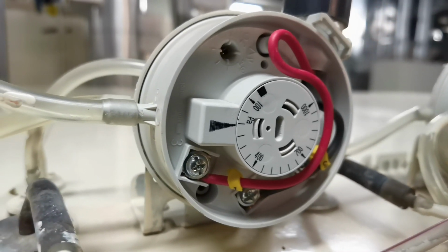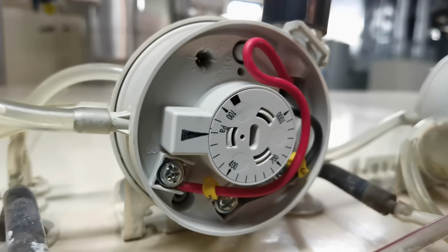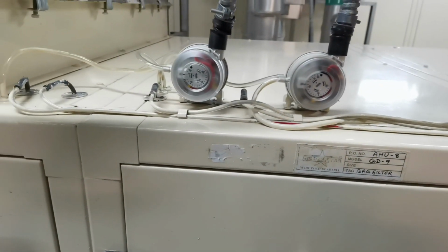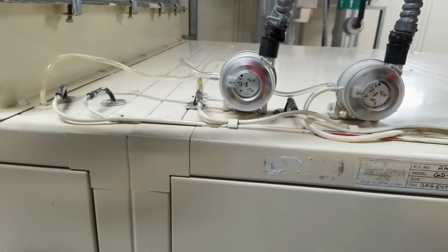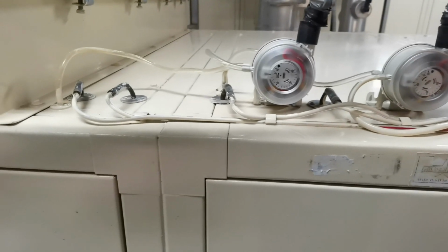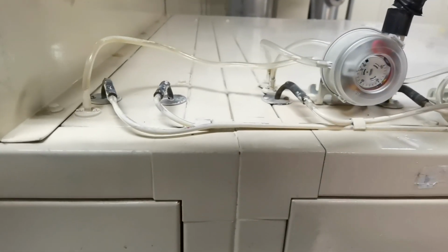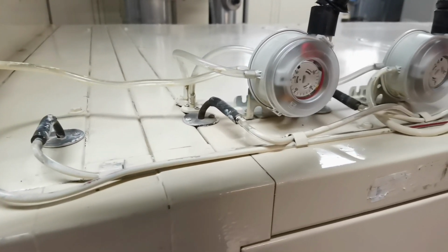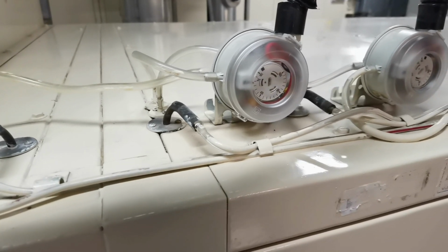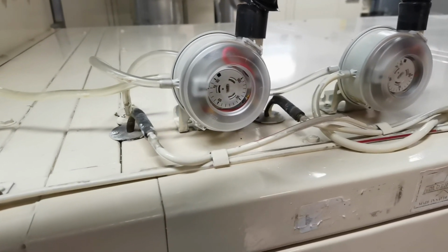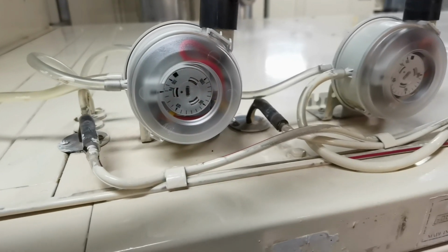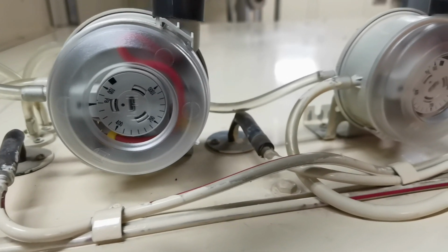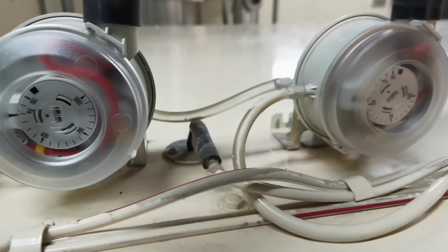This is the actual differential pressure switch installed in the AHU for the pre-filter and bag filter status. As you can see, the plastic tubing connected to the AHU is separated according to the positive and negative port connection of the differential pressure switch. The pressure connection tubes can be any length, but the response time increases if longer than 2 meters. So we already have a filter monitoring sensor. We will connect it to the DGP later after we finish all our tasks.